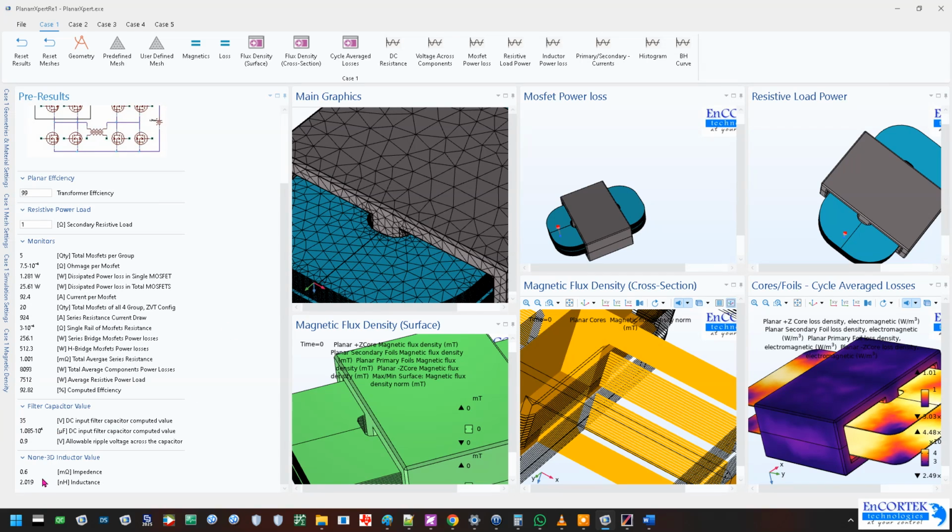So we have the impedance at 0.6 ohms, and lots of the energy goes across over here. This 0.6 ohm has some energy across it, and not much going into the transformer, but we could see we have some losses here because this is 600 micro ohms, right, which could be greater than what we have here as a MOSFET.